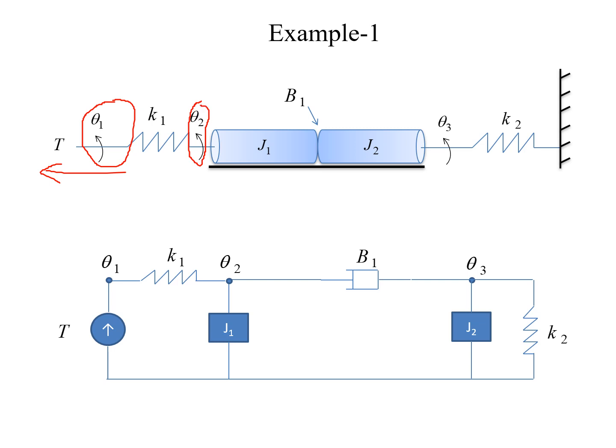So here theta1 and theta2 are the displacement that we have for the spring K1, and now this is connected to an inertia element, and since these two inertia elements which are represented as J1 and J2 are connected without a dashpot or a spring, you will have a friction here which is represented by B1. Friction coefficient could be taken as either C or B. So here it is represented as B1. So that should be represented with the dashpot.